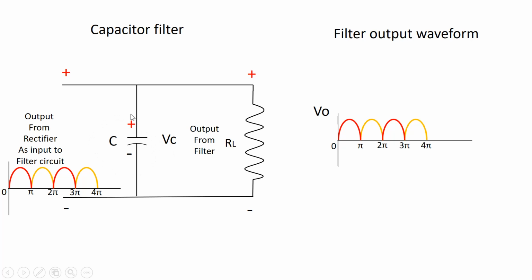The characteristic of this capacitor is that it has very good charging and discharging characteristics with its own time delay of the charging and discharging networks. Other than that, it has its own opposition to the flow of AC and DC quantities through it, which is given by the equation Xc = 1/(2πfC), measured in ohms.